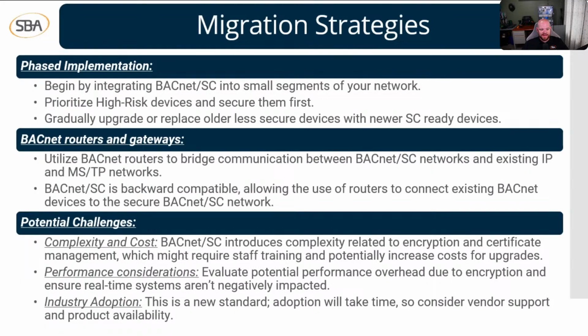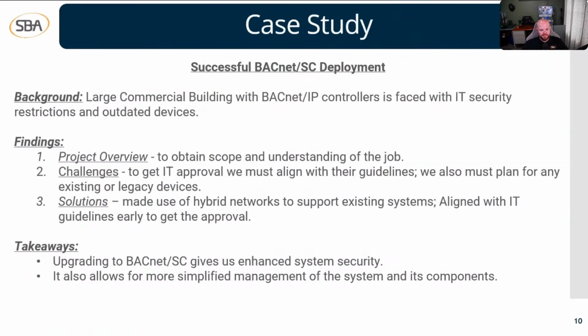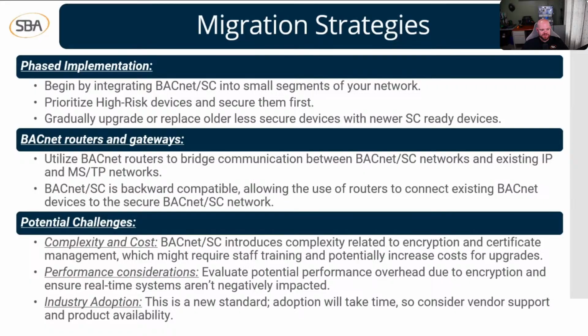The next thing here is that BACnet SC is backwards compatible, which allows us the use of routers to connect existing BACnet devices to the secure BACnet SC network. This is just talking about BACnet SC. We still have the ability to tie in with our BACnet IP and BACnet MSTP devices as well. So that's BACnet routers and gateways.